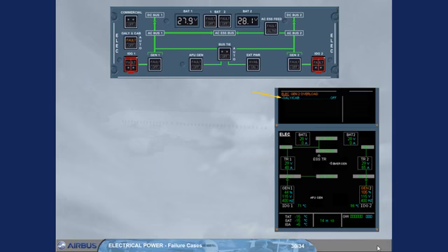So, we did the action for you. Observe, on the ECAM ELEC page, the white GALLEY SHED appears and the load indication has returned to normal. Note, all galley circuits, and if installed, the in-seat power and the IFE systems are not supplied.